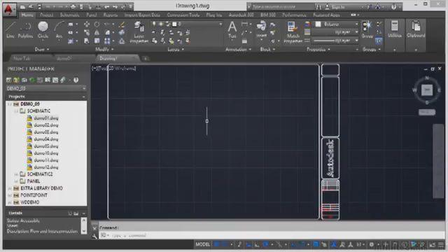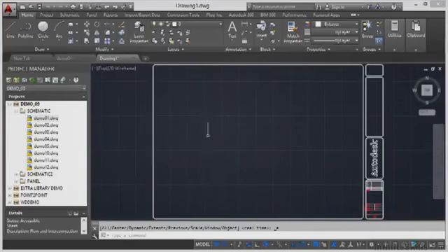And what I'm going to do now is double-click on the wheel on the mouse, centralize it, just switch off the grid and the snap, and I've done a zoom extents on the mouse as well. So that's all done. Now what I need to do is save that drawing to the AutoCAD Electrical project folder. So you'll remember we put Save As on the Quick Access toolbar in previous videos.